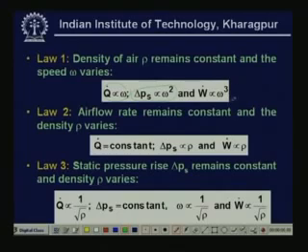Remember that omega is the rotational speed, revolutions per second or revolutions per minute or even radians per second. So, the power input is proportional to the cube of rotative speed, the static pressure rise is proportional to the square of rotative speed, and directly proportional as far as the air flow rate is concerned. So, this is valid for constant air density, right.